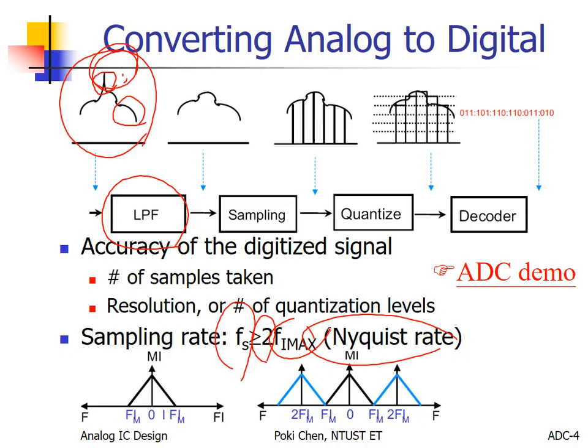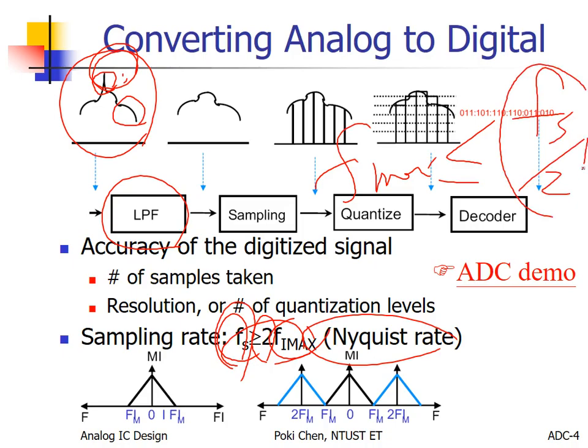So if your sampling frequency is fixed, then on the contrary, what is the maximum input frequency for you? Oh, you can see here. The maximum should be less than your sampling frequency divided by 2, right? And beyond that, what will be the consequence? It will hurt your original one. Okay, we call it aliasing.